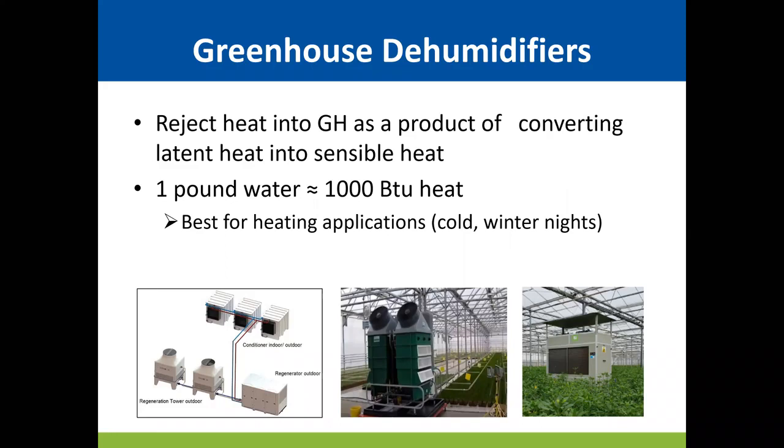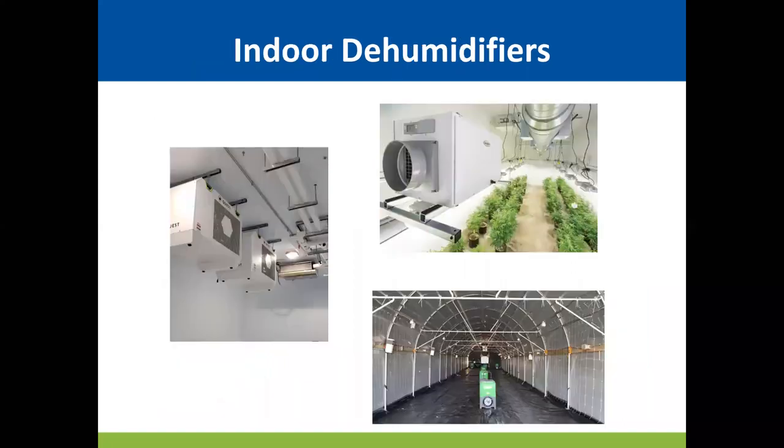There are some new technologies coming online, like this one that's also using liquid desiccant that rejects that heat to the outside using cooling towers and chillers. You can also use chilled water or refrigerant to do this, but the key is you have to reject the heat outside, so you're only doing dehumidification, say, in the summer when it's hot and humid inside. Indoor dehumidifiers, I'm sure most of you are familiar with a lot of these technologies, right?